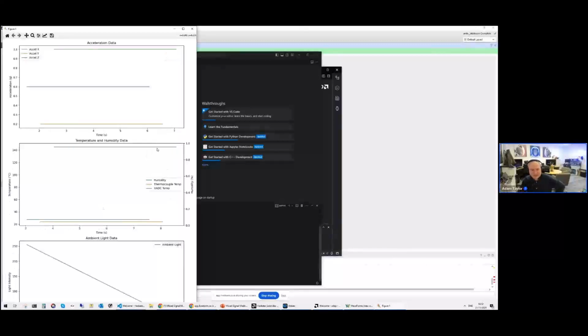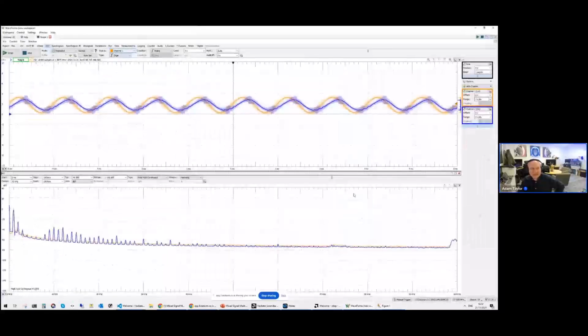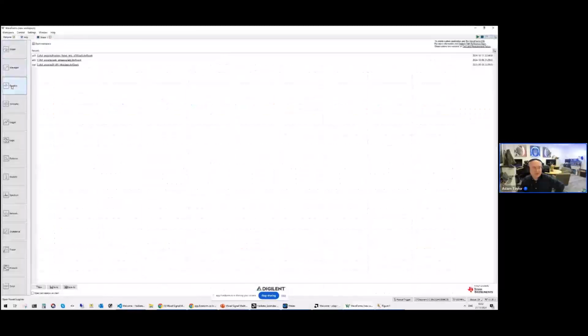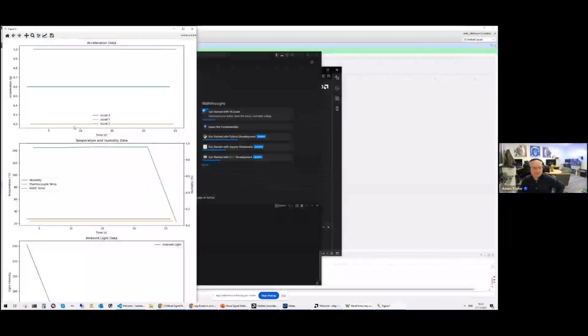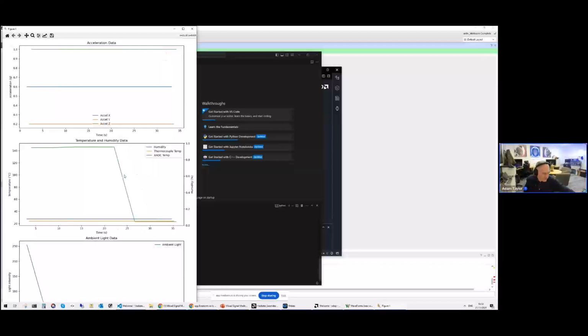It's sending data back. As you can see at the moment, the XADC's writing out some really crazy value for the temperature because it needs a supply voltage applying to it to actually bias the RC. Once you get that, it'll come in close to what the other temperature is. And if I just hold this and change the value of it, we should see it again. As I increase the temperature, we see the XADC changing and measuring the values.